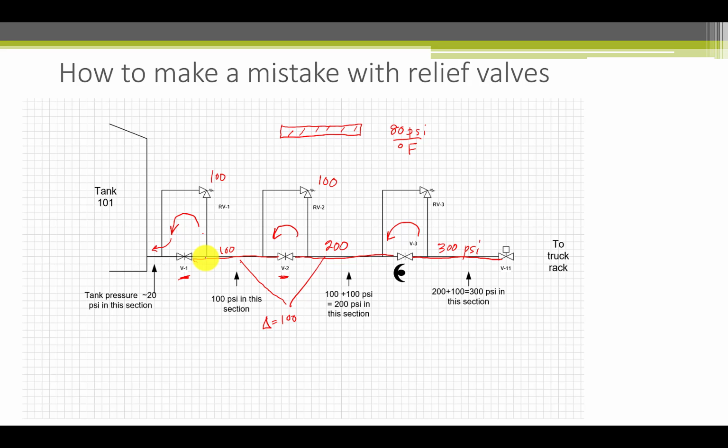So your intent to keep the pressure below 100 has actually resulted in a far excess of your limit of 100 psi. There have been cases where, say this is a 90-degree valve to open to a tank truck, for example, to fill it with gasoline. There are people that have broken their wrist because such a high pressure was in this segment that when they opened the valve, it just slammed open and busted their wrist. So being aware of this is important. It's a safety issue, and I recommend that you put thermal reliefs wherever the liquid can be blocked.